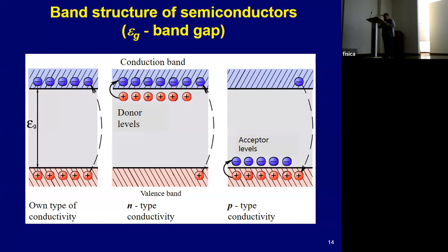The depleted layer of a semiconductor detector is created as follows. A layer of n-type substance with electronic conductivity is deposited on the surface of a p-type semiconductor, which has hole conductivity. By diffusion, electrons from the n-type semiconductor will be introduced into the p-type semiconductor, and holes will go in the opposite direction. Similar reasoning can be carried out if a layer of p-type substance is deposited on an n-type semiconductor.